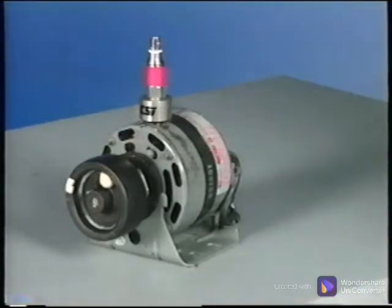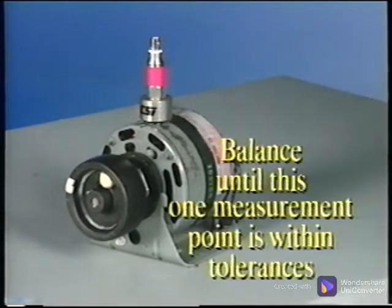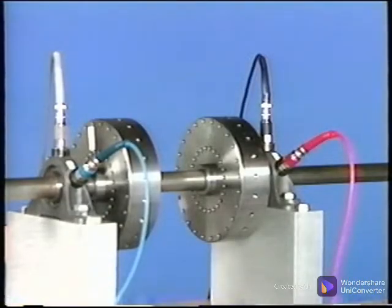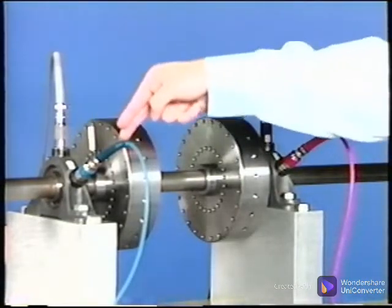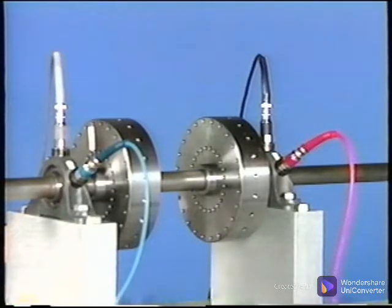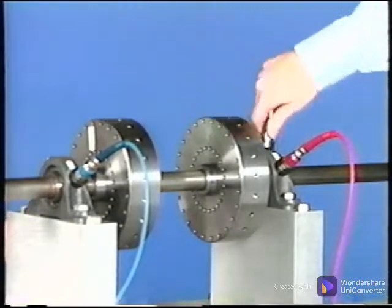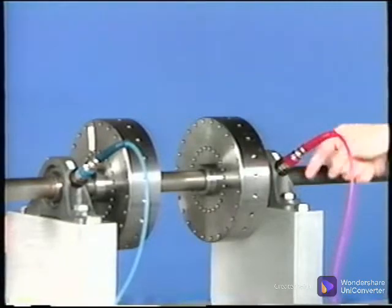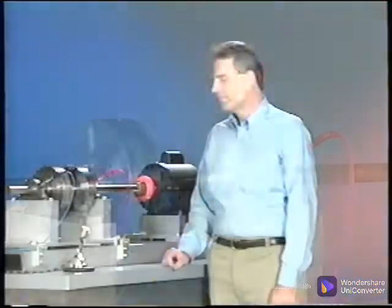On this single plane rotor kit, using only one measurement point, the effect of additional weights is measured at this point, and the balance procedure continues until this one measurement point is within tolerances. On this 2-plane rotor kit, however, we must place weights so that all measurement points are within tolerances. If only one measurement point is to be used at each weight plane, select the direction that has the highest amplitude of unbalance. This will typically be the horizontal direction for machines with vertical hold-downs.